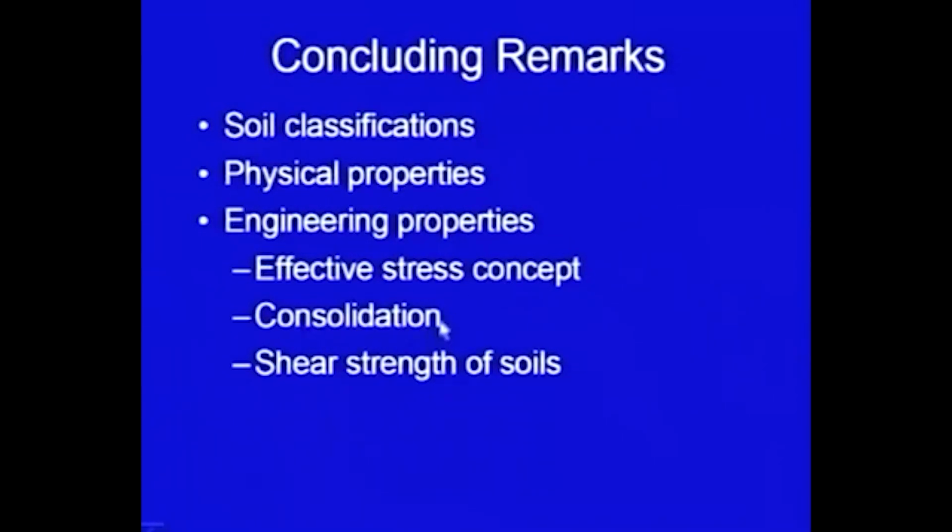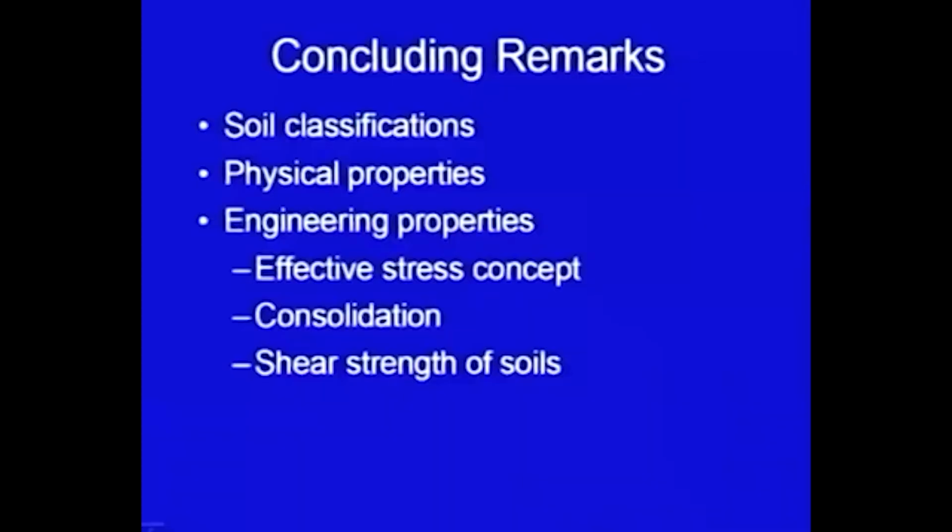Then we have discussed the consolidation of the clays. It is a time dependent phenomenon, and wherever the clays are there, you should expect to get time dependent settlements. So, we have discussed this also. And finally, I have discussed the shear strength of the soils. We have used the Mohr-Coulomb linear failure criterion. We have discussed how to do the shear test, the triaxial strength test, and how to compute the shear strength parameters. So, with this I conclude chapter 1.